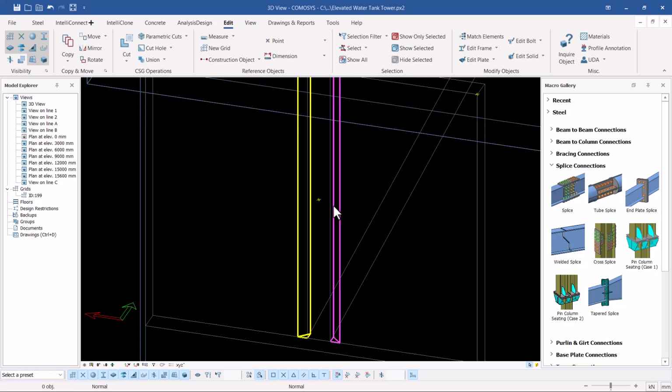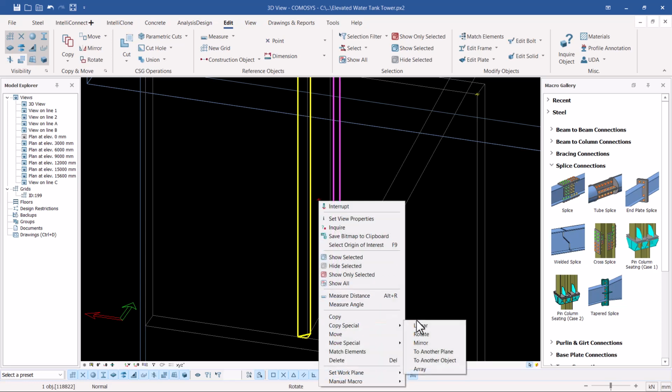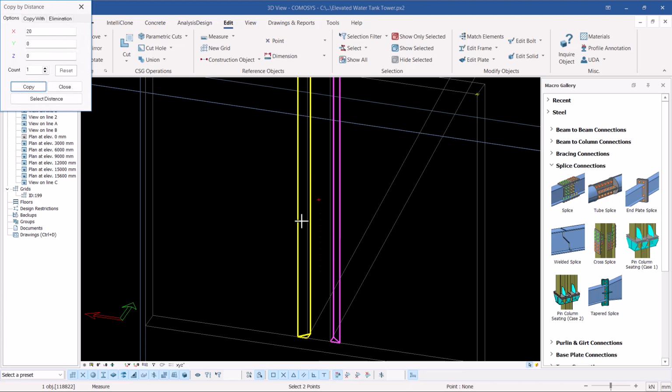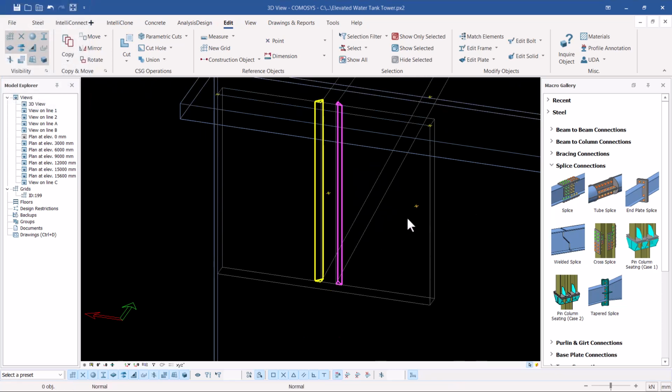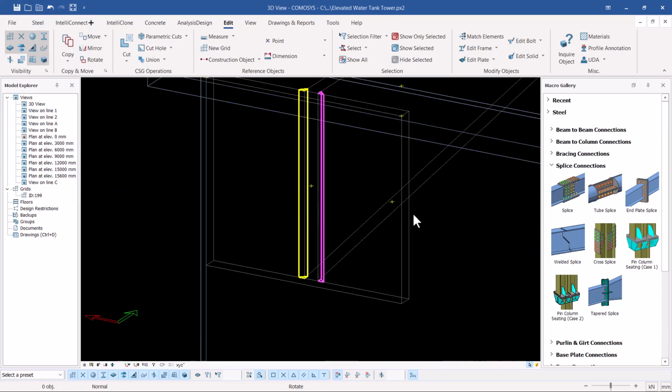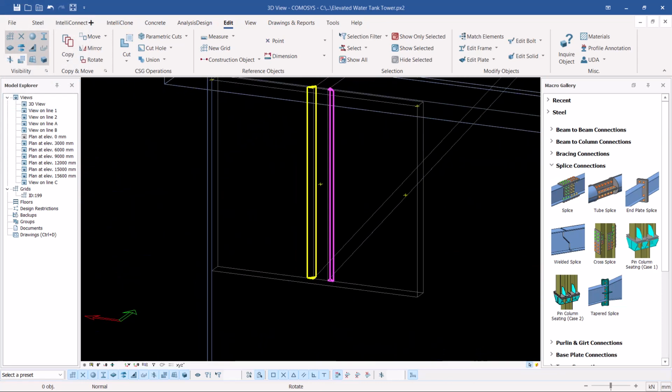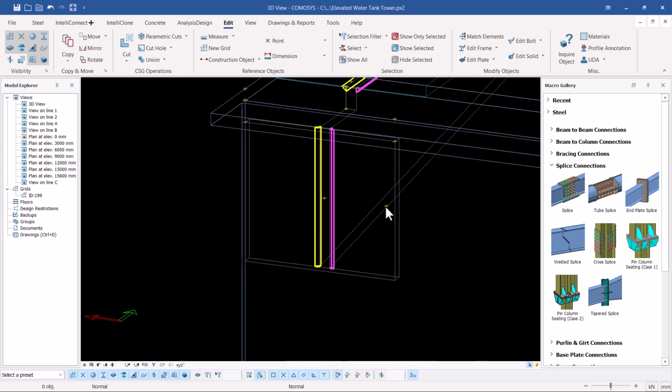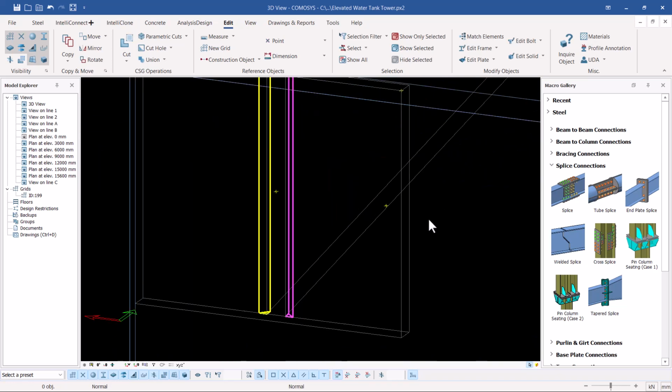So I'm going to select this point, right click and come to special copy and give it an offset of maybe 60. This is our absolute point, and now we are going to create a relative point that will be relative to this point here. Now I'll give it an offset along the x-axis, but in the opposite direction. Let me just give it 60 and see where it will end. That's it. If I close that and turn that around like that, I think you can see this thing clearly because it is in a different draw or display.